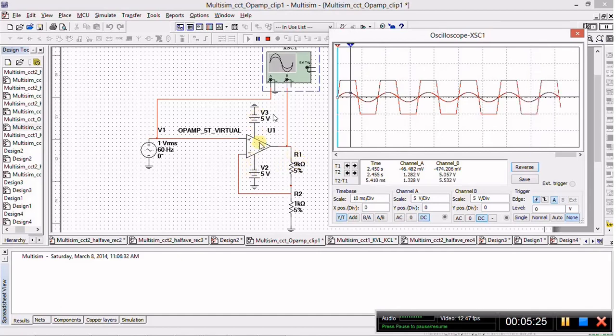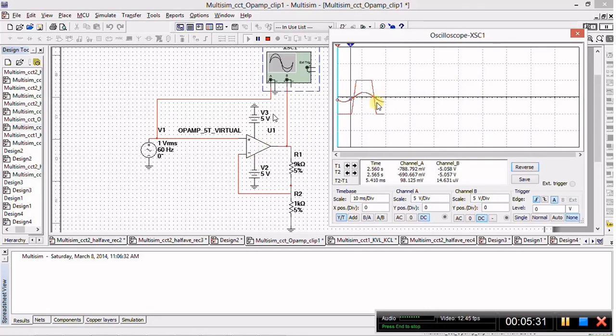We have a source of 5 volts driving our op amp. Therefore, the maximum limit we can get at the output is 5 volts. So even though we'd be expecting something around 10 volts, we'll actually be getting 5 volts due to clipping.